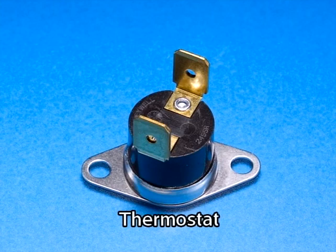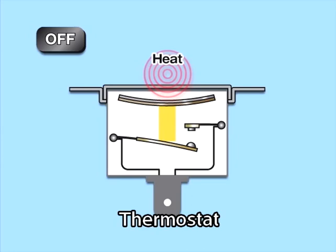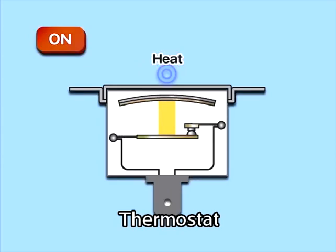The thermostat is a device incorporating a sensor and a switch. The device is turned on or off by a contact switch set to operate at a specific temperature. While there are various types of thermostats, the disc-type bimetal thermostat is the most commonly used. Two types of thin metal plates, each with a different thermal expansion coefficient, are stuck together to form a bimetal. This deforms when heat is applied and returns to its original shape after cooling down. Expansion or reversion of the metal disc causes the switch to turn on or off.